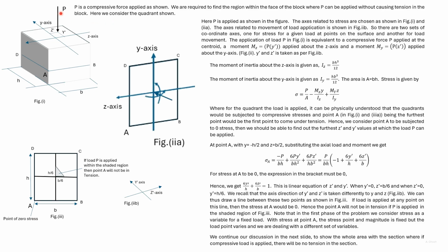Now, the load P, which is eccentrically applied, is equivalent to a centroidal force and two moments about the axes of symmetry as shown. As earlier, we choose the z-axis in the same direction as the moment vector of this moment, and the y-axis in the same direction as the moment vector of this moment about the vertical axis.